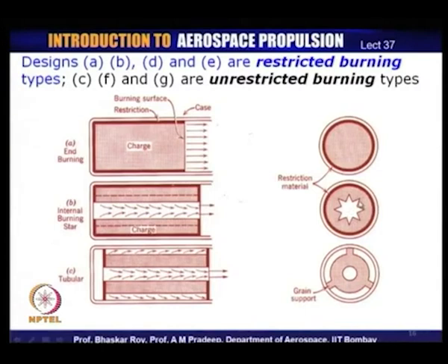Compared to, let us say, a circle, the surface area of this star shape is substantially more than any shape that you put here, whether circle or ellipse or square. A star shape has more surface area of burning, and this gives you faster burning. So, the star shape has been created for enhanced burning capability of the rocket.